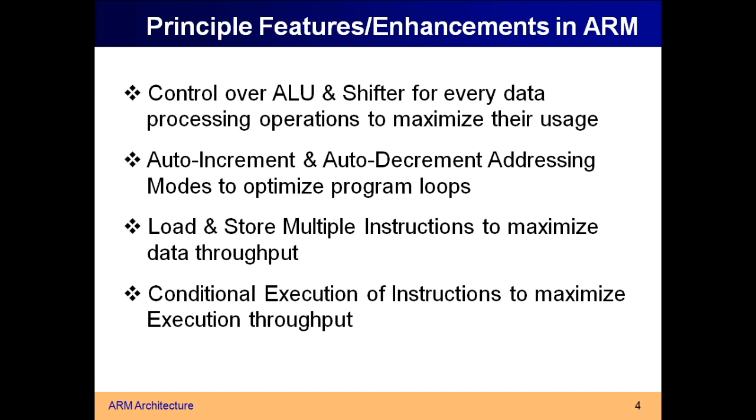So if you are using instructions using this auto increment or auto decrementing addressing mode, automatically the incrementing or decrementing will be taken care. You don't need to manually do it. Right? If you are using that instruction, automatically it will increment, and whenever the condition is satisfied, it will stop. That is known as auto increment or auto decrement addressing mode.